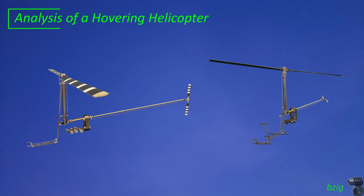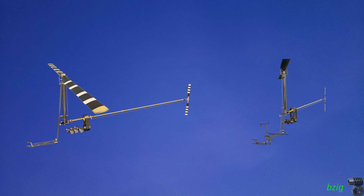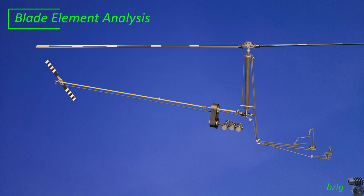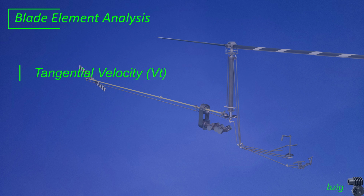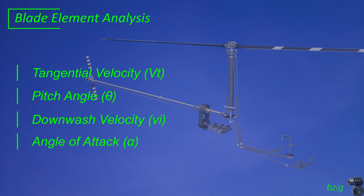Airplane wings don't rotate or flap like helicopter blades, and while airplane engineers have to account for downwash, at least for subsonic flow, it's relatively small and constant along the span. This isn't true for helicopters. Helicopter engineers, on the other hand, have to account for these things, and these things mean that unlike an airplane wing, each part of the rotor blade sees a different tangential velocity, pitch angle, downwash velocity, and angle of attack.